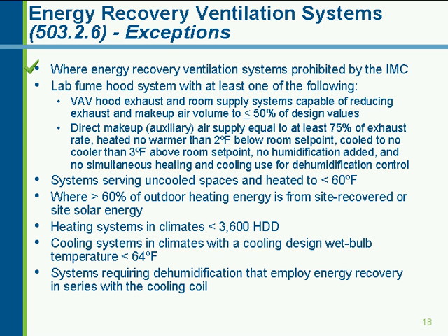If you've got a laboratory fume hood system, you've got some alternatives. Instead of the energy recovery ventilation, you can install a VAV fume hood exhaust system that reduces the flow from that system to less than 50% of the design value. That gives you an exemption.